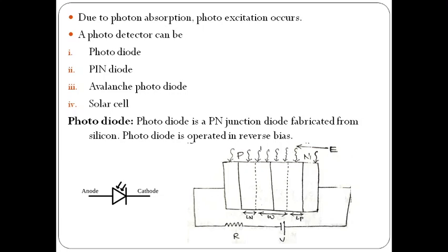The depletion region width is very small, so the current will produce due to the drifting of electrons and holes as well as light intensity, and this electron to hole pair generation is very small compared to this forward bias supply. So it is very difficult to identify the current due to the light. So in forward bias, it is negligible current due to the light. So we cannot notice or identify that current due to the light intensity.